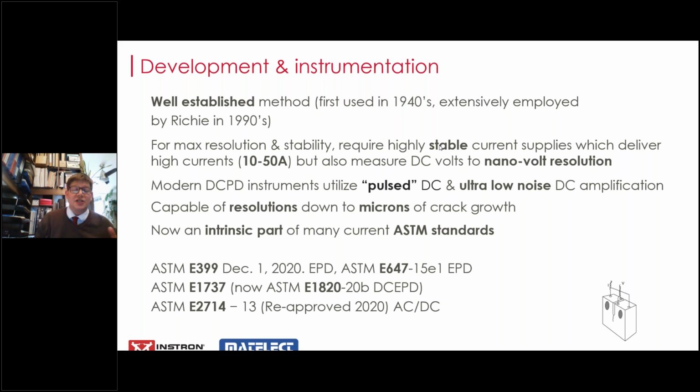With the changes in technology, so has the technique changed. But the bottom line is that you need to have a relatively large current flowing in a specimen to produce a large enough voltage, because of the good conductivity of the metal. So quite typically now PD systems use 5 to 10 amps to get a voltage which is stable and reliable, whereas in the past this has been hundreds, if not thousands of amps, to get a sensible value.